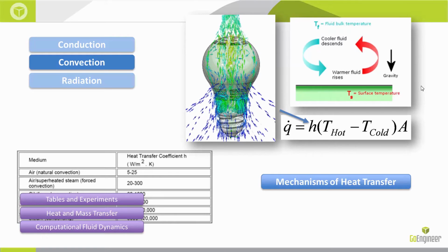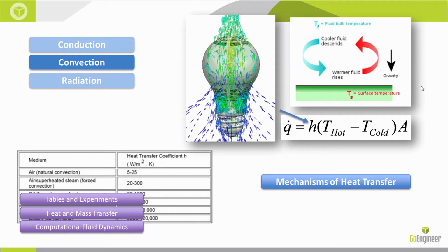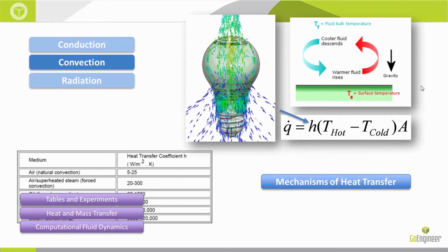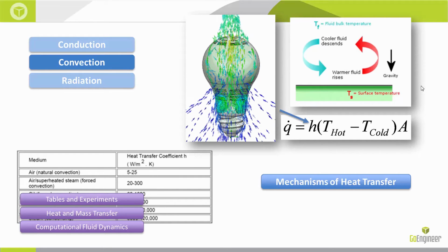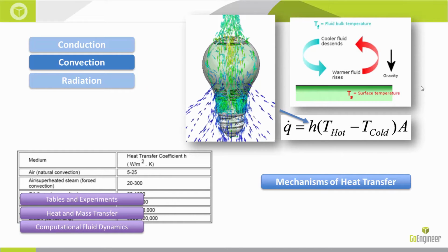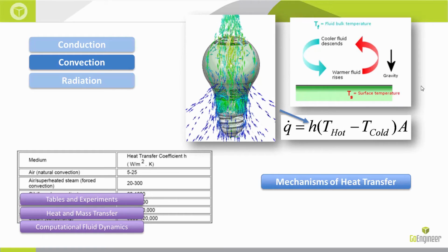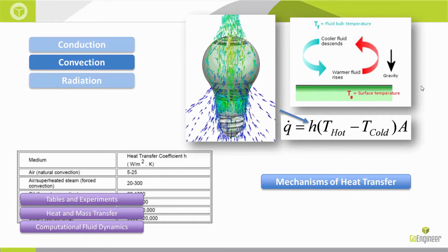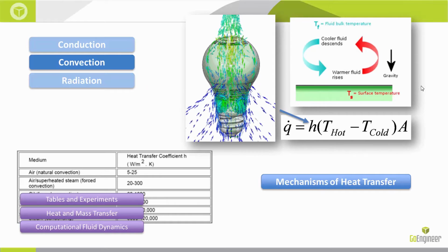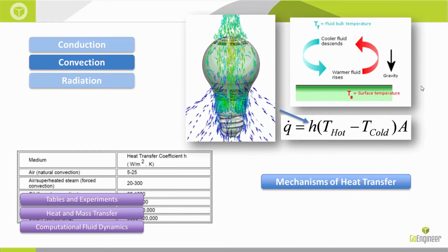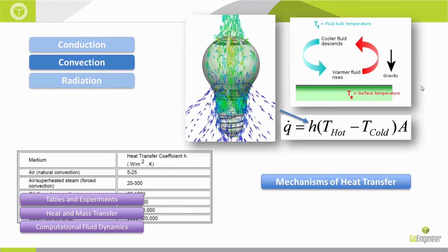And finally, the most robust and the quickest way of avoiding using the convection coefficient, but being able to program both the solid medium and the fluid medium in an analysis software, is to use the CFD or computational fluid dynamics software that essentially avoids this entire convection coefficient definition. It calculates this heat transfer coefficient for you when you run this sort of fluid solid interaction.